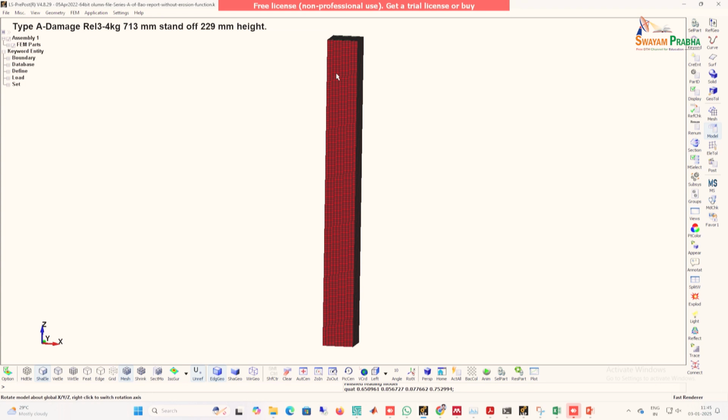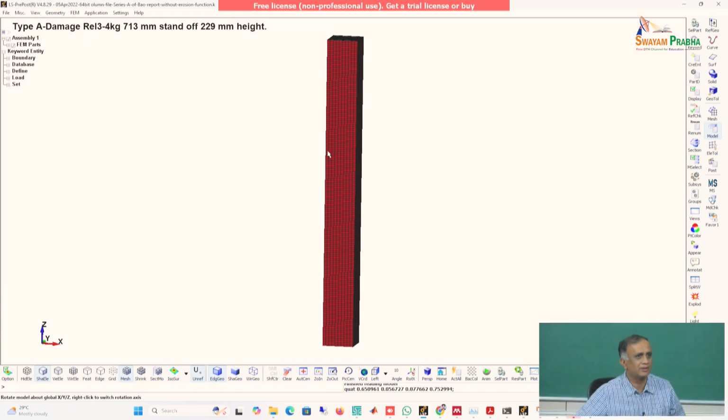It basically represents the volume divided by the volume when the determinant goes to 0, or negative volumes, they just fold into each other, right? Then the simulation does not proceed. And it could happen. You could have 1,000 elements, and if one element gives you a negative Jacobian, the program doesn't ignore it, it continues.